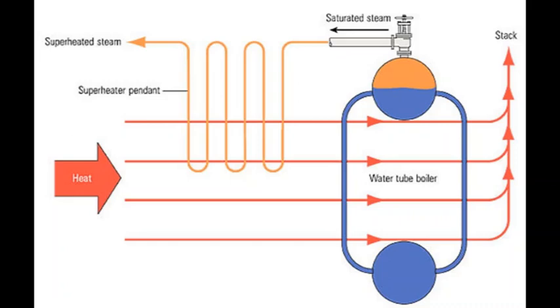So we get water steam mixture which is again entering the drum, and while entering there are separating arrangement, and this separating arrangement separates the water within the steam water mixture, and separated steam in saturated condition come into the steam space, and from there is arrangement to dry the steam and clean the steam from moisture, and dry saturated steam comes out of this to go for superheating.